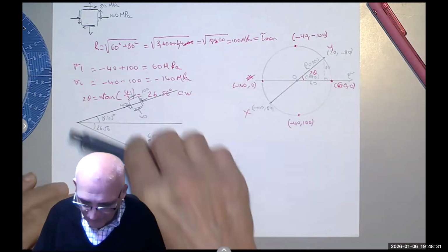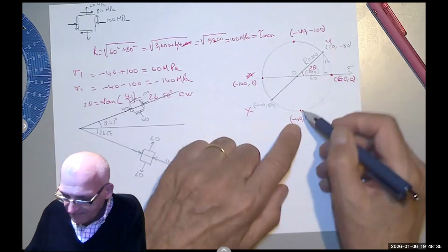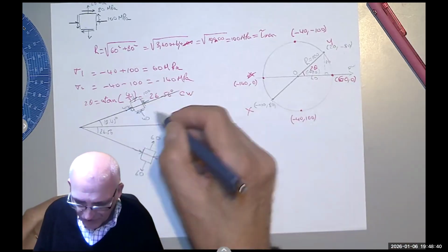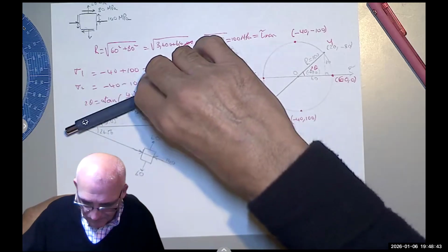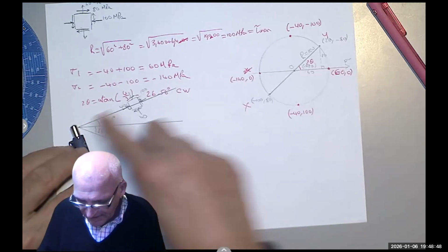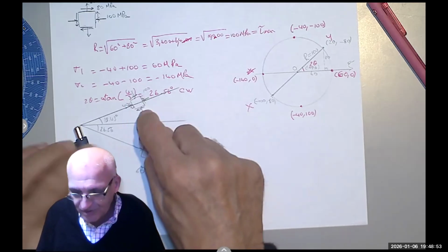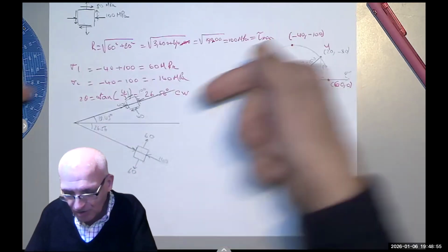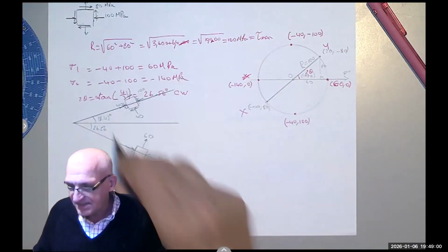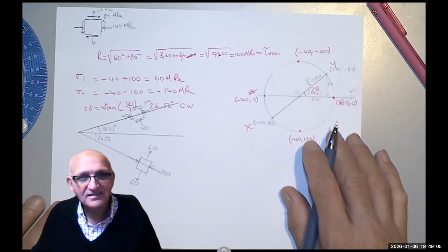Notice, as I said, I could have rotated 45 degrees and come to this. So the y would have been having positive shear. So these would reverse. If I rotate this 45 degrees and another 45 degrees, meaning I make it perpendicular to this line, all that will happen is that these arrows would reverse. On the y, they would go counterclockwise. On the x, they would go clockwise, but the negative 40 would stay the same. It doesn't matter. Okay, I hope this wasn't that bad.